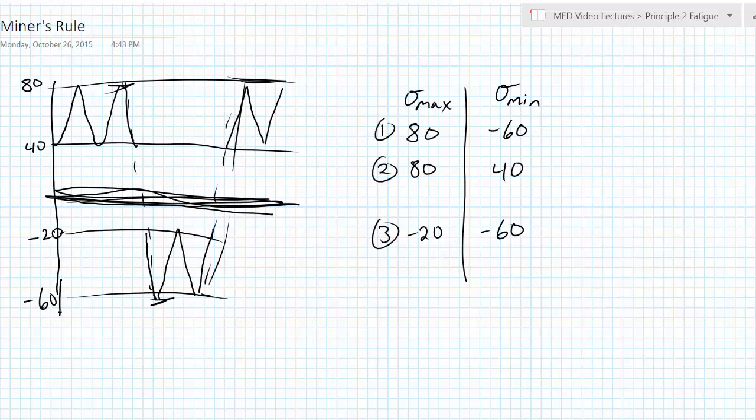So the hardest part about doing cumulative damage or multiple cycles is figuring out where the cycles are. There are lots of different methods for doing that. If you're just looking at data, usually you can take frequencies, and you'll find, first of all, the primary frequency, that's the largest one, the biggest difference between values. Once you take that out of the picture, then you can look at the next one, and so on like that. If you're doing this in the field and you're taking experimental data, you'll often see lots of vibrations. And the smaller the cycle is, the less likely it's going to be damaging the part. So what's most important is to catch the biggest cycle.